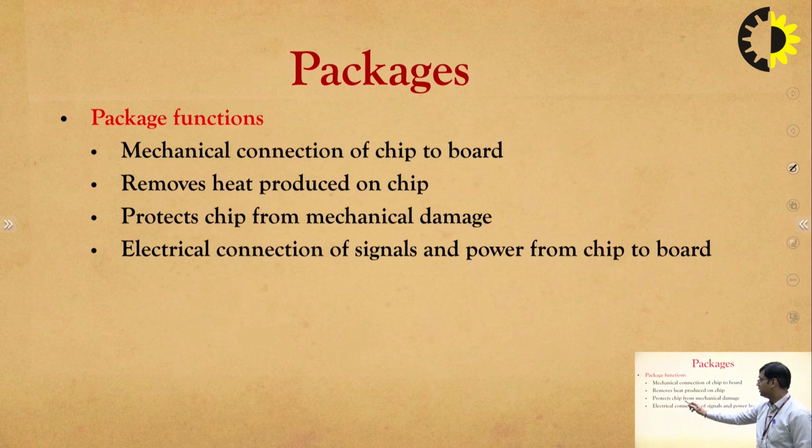Third, packages are used to protect the chip from mechanical damage. As we know that VLSI chips, which are made up of semiconductor, are very fine and consist of millions of transistors. So, they need to be protected from mechanical damage, and for that the VLSI chip is encapsulated with the help of package. And another important function of package is that the electrical connection of the signals and power from chip to the board is done with the help of packages.